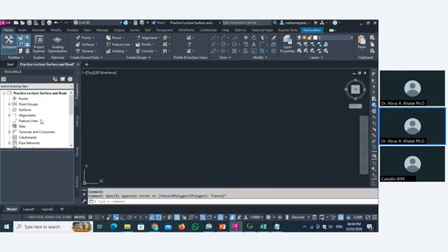Once you have your assembly, you can make your corridor and assign that assembly to the corridor. Once you have your full corridor in working condition, you can view that corridor in different section views. Then you can calculate your quantities and materials, create your design sheets and send all the sheets to the client. You can also export all the results in Excel files or web files.